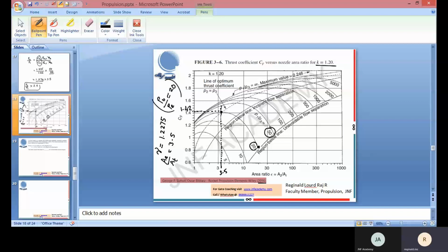The pressure ratio is around 2.5 times. To create that pressure, you need more propellants, a lot of energy. But the addition to thrust that you get is very small. From the figure you can see something like 1.5, right? So though you're increasing the pressure from 20 to 50, above the optimum you get a very small pressure thrust contribution, which will increase the CF. So this also tells you that the CF is going to increase as you increase the pressure ratio.